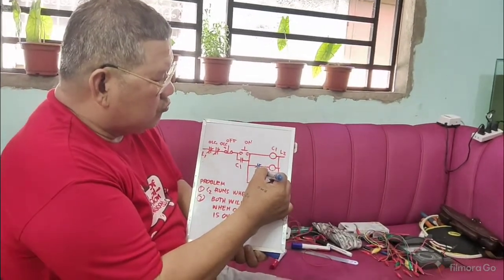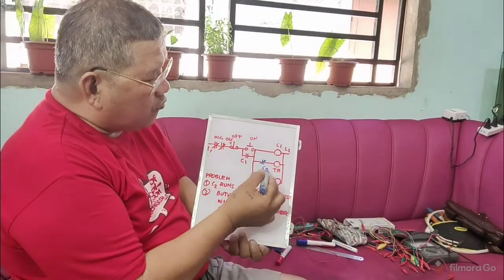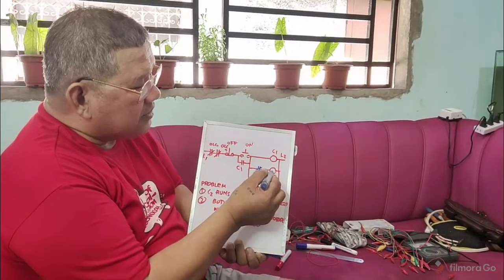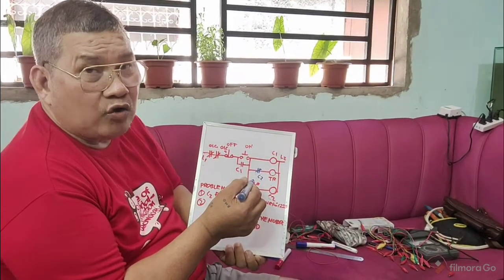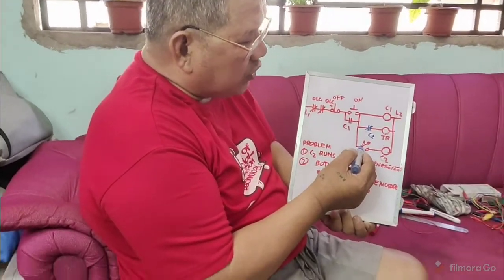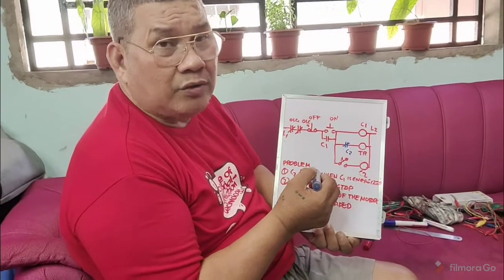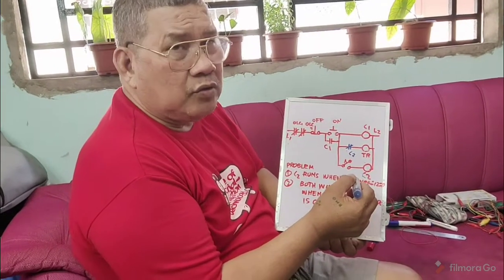Conveyor 2. So when this is energized, of course this will open and this disconnects the time delay relay magnetic coil. Once this is disconnected, what will happen to the contact here? It will go back to normal position. Then what will happen to your conveyor number 2?